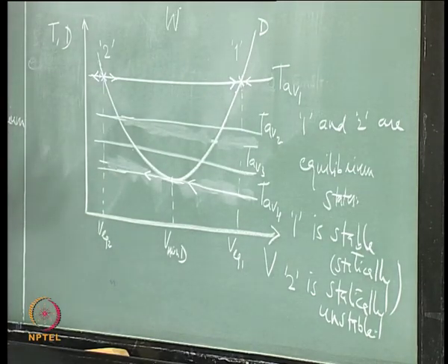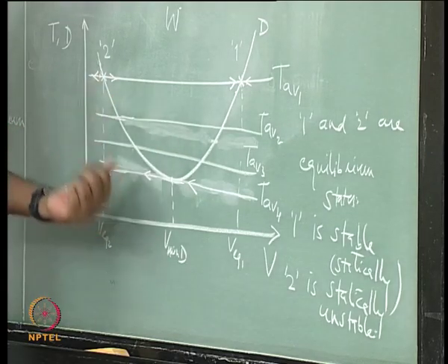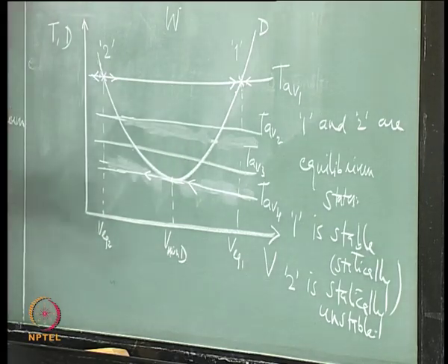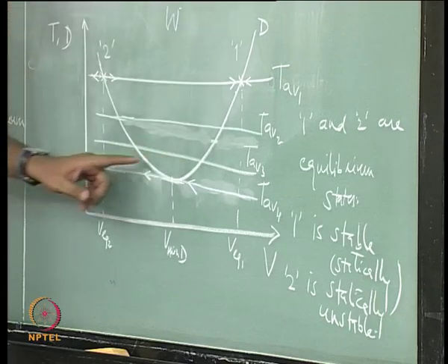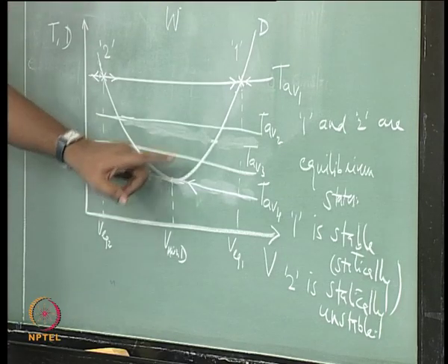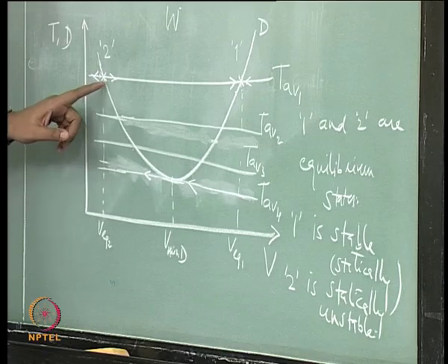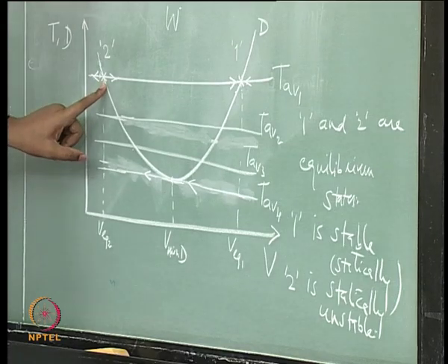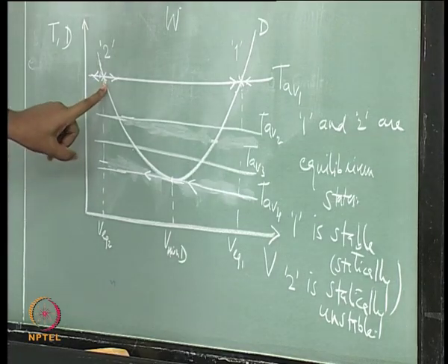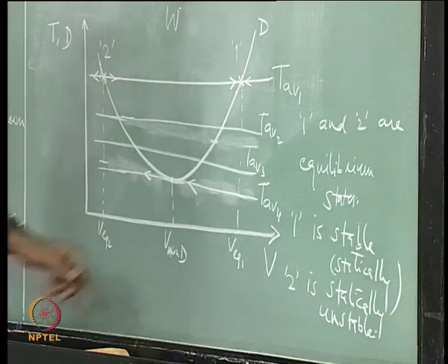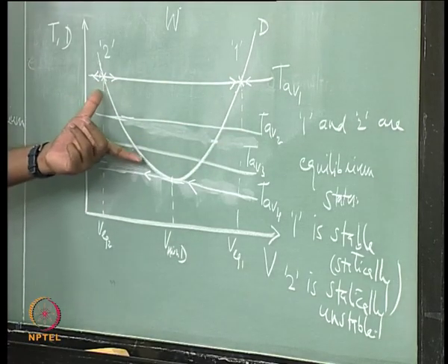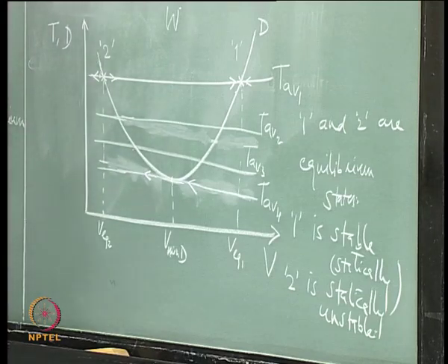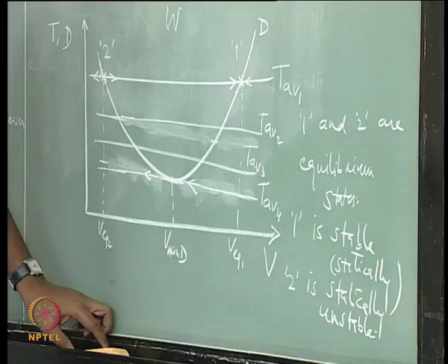What this tells us is that the whole of this part of the curve, where we can find several trim points by changing the thrust available, is not available for flying, they are all unstable, and on this side it is all stable. In reality this is not what happens, and we will talk about it when we come to dynamic stability.